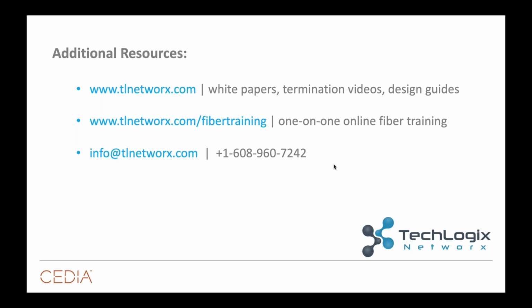This is where getting a test kit, where you can actually meter the amount of loss on your actual runs, is useful. But if you're only doing a couple of installations here or there with fiber, until it becomes that everyday installation, I tell guys, the VFL, it's a laser. It's going to come with your toolkit. It's going to test your connectors. Get the meter and the test kits down the road.